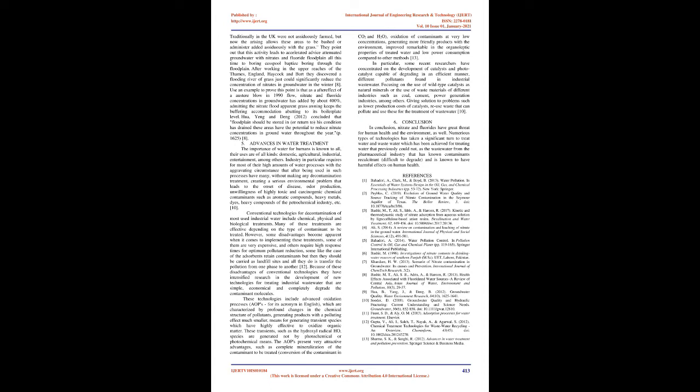Because of these disadvantages of conventional technologies, research has intensified in the development of new technologies for treating industrial wastewater that are simple, economical, and completely degrade the contaminant molecules. These technologies include advanced oxidation processes, AOPs for its acronym in English, which are characterized by profound changes in the chemical structure of pollutants, generating products with a much smaller polluting effect, by generating transient species which are highly effective to oxidize organic matter. These transients, such as the hydroxyl radical HO, are generated by photochemical or non-photochemical means.